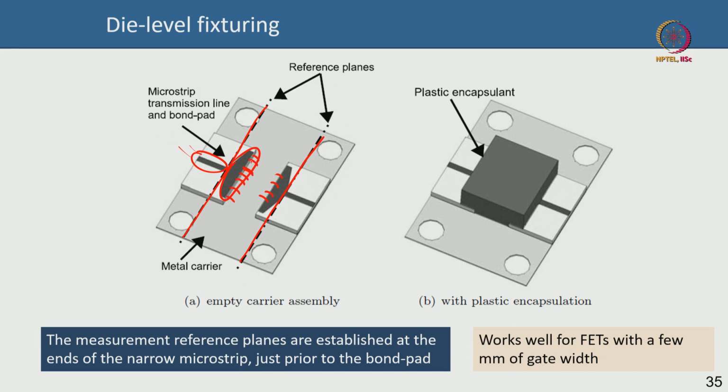Okay. So, these bond wires and bond pads could be a part of the actual device that you are going to sell or give to the designer or the customer. So, they could be a part of the device. So, you are going to de-embed till this plane, for instance, everything till this plane you might have to de-embed. In some cases after you put down the device, sometimes people put plastic encapsulation, like an over-mold, you can fill in with plastic everywhere. It protects the device, it gives good protection against mechanical vibration, dirt, etc. Again it depends on the particular application, depends on the power levels and things like that, but you can choose to have this encapsulation on top of that, and then you have to de-embed till this point.